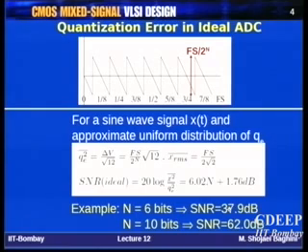These values of SNR are not very high if you look at linearities, but anyway this is what happens. In a fully analog system, achieving linearity or THD values above 70 dB is not very difficult. But here, even if the ADC is ideal, the best performance which can be achieved is, for example, for 10 bits, 62 dB.